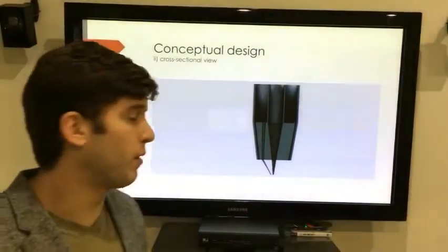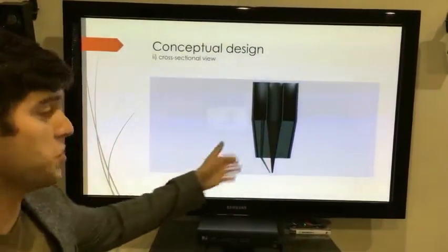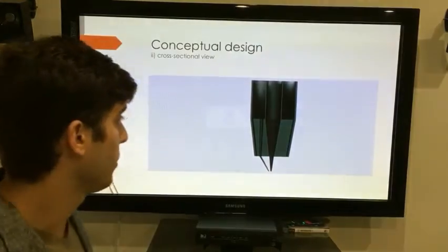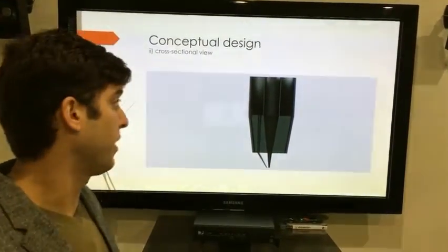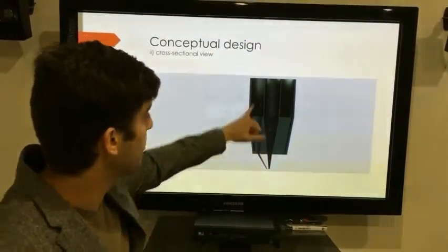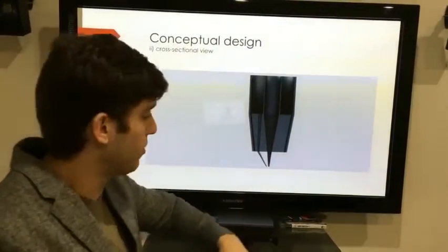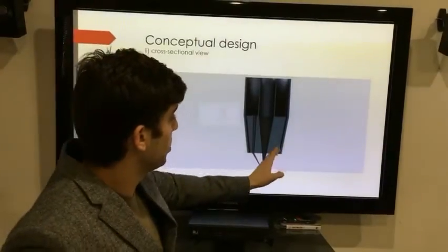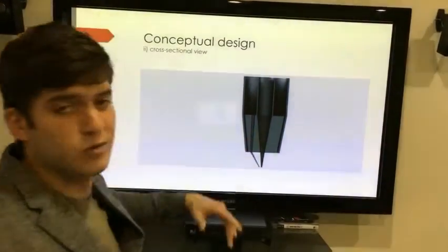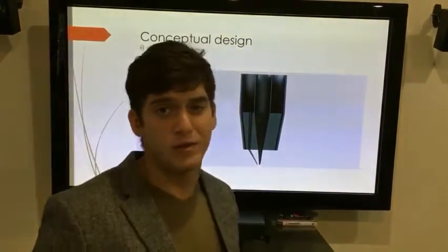And on this slide right here, I'm showing you a cross-sectional view of our conceptual design, which is basically to show you where the laser goes, where the powder is coming from, where the point is that they're going to go together in order to weld, and where the shielding gas nozzle is, which is normally internal on a laser beam welding machine.